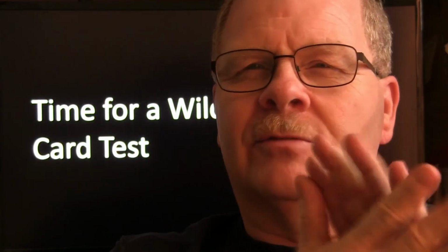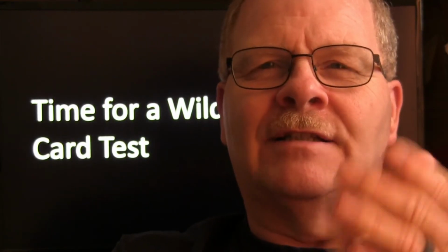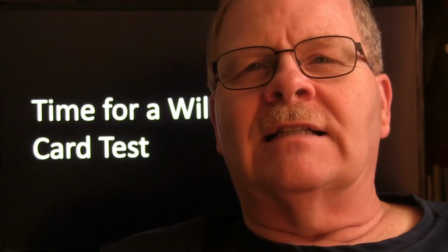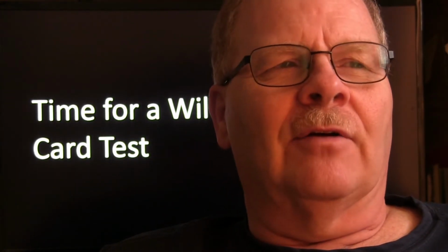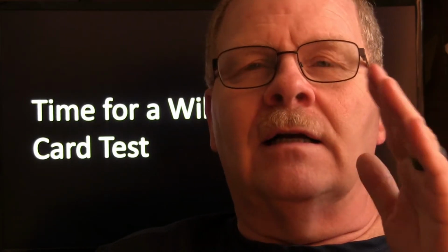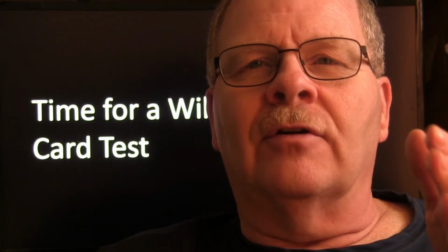Cleaned them off, made it real smooth, scrape, sand, put a new head gasket on it, put it all back together, put the intake back on it. Started on it at 10 o'clock, started it up at noon. And he was so shocked that I got through with it so quick.